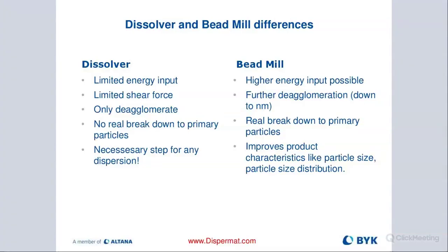If people just mix things together and think, okay, I can put everything into my horizontal bead mill, there is an agitator that's in the supply vessel that won't do a good job mixing, you're going to probably end up with a clogged screen or a clogged dynamic gap. And then you won't be able to circulate your product through the mill, and you're going to be ending up cleaning it out and causing more work for yourself than you would have had if you had done a good job properly pre-dispersing the material.